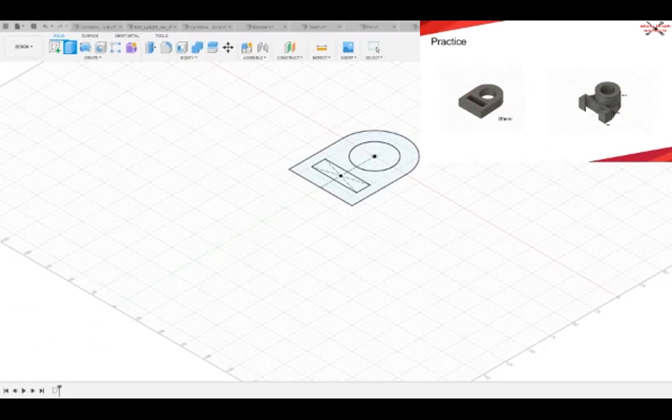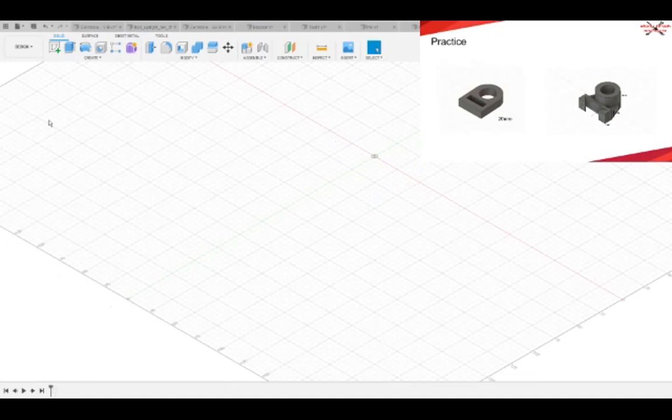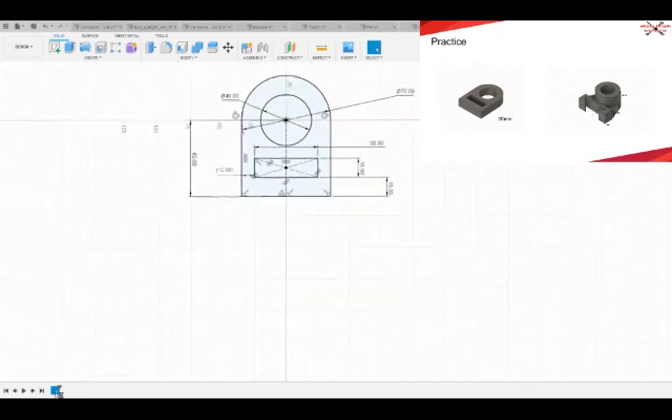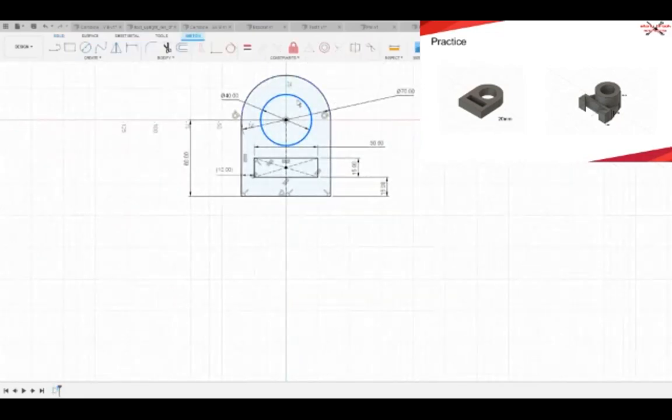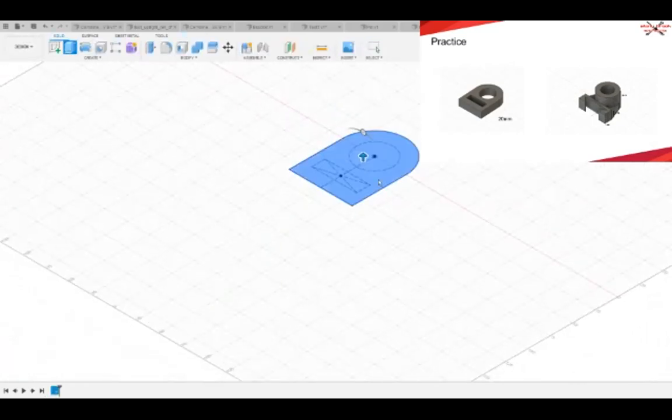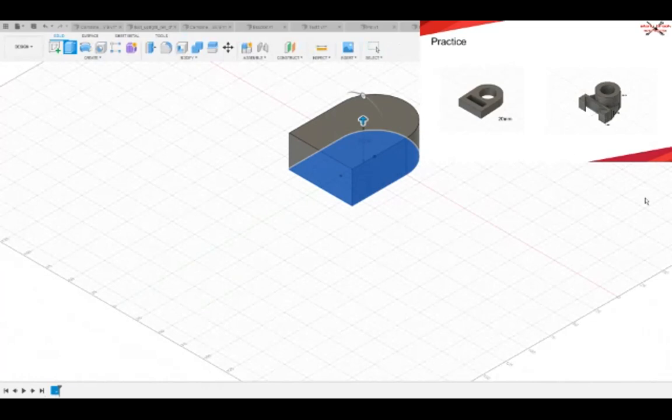For example, if we edited this sketch for a minute, hypothetically, let's go back. I accidentally undid it. There we go. So let's say hypothetically we made this one for construction, and we made this one for construction, such that these are no longer a part of the sketch's geometry, but rather, quote, reference lines that you can put back into place whenever you want. So there's that, and there's that. So we finish the sketch, and we move on to extrude. Now it's a single closed contour that's just a little nub.